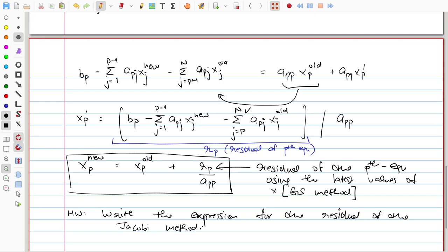It's not converging. Ideally, in an iterative technique, your residual should show a behavior where it goes down with iterations. Well, the method that you are implementing is not correct. I mean, see, one major thing in CFD that people deal with on a daily basis is that residual does not go down. That's our daily problem for those who work in CFD.